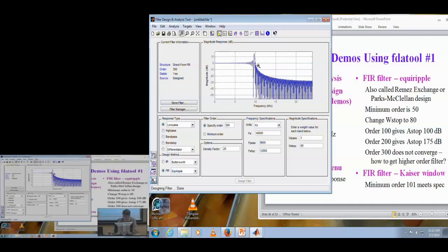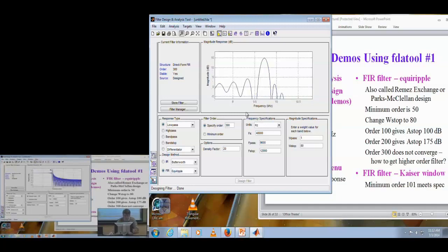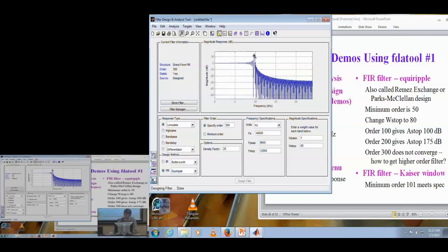First of all, it didn't converge, so we can't really rely on this answer. But if we look at it, it's got some basically incredible amplification of this frequency. And the amplification at about 9.7 kilohertz is about 15 dB. If for some reason we were to say, let's just use this filter, would it function if we were to only pass frequencies that were close to DC or really high frequencies? Well, who knows if maybe there is some use in the world for this kind of filter.